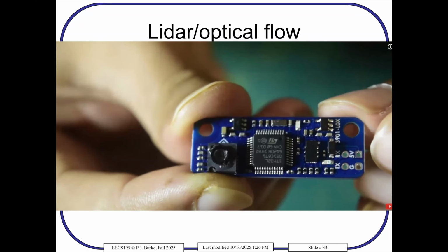However, it gives you much better resolution on the altitude than the barometer. The barometer is half a meter. LiDAR, I think, is a centimeter or less. So let's try LiDAR-based altitude hold in the drone cage and see if it works. So it's coming. So the LiDAR chip is, well, so let's take a look. Just like everything else, there's a microcontroller. It's an STM32. There's some firmware. Okay, we're not going to worry about the firmware. We got enough firmware we're doing. And let's just use the stock firmware.